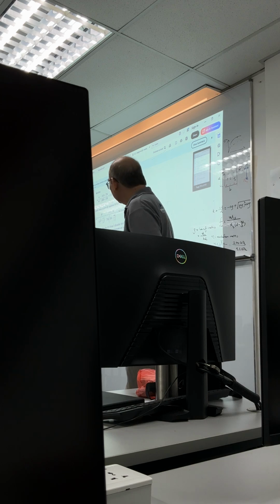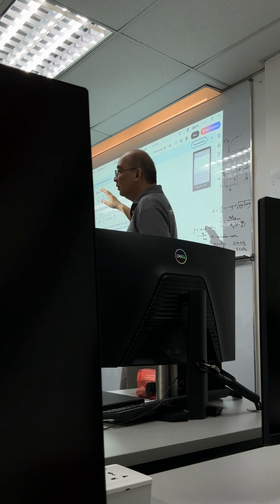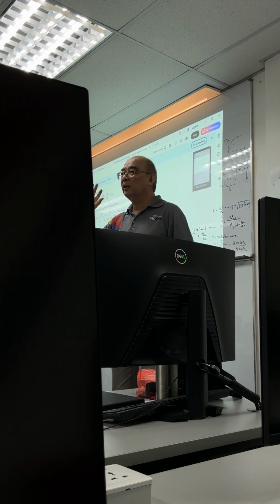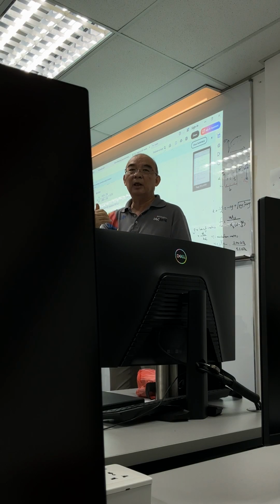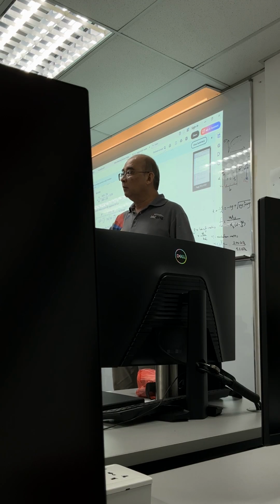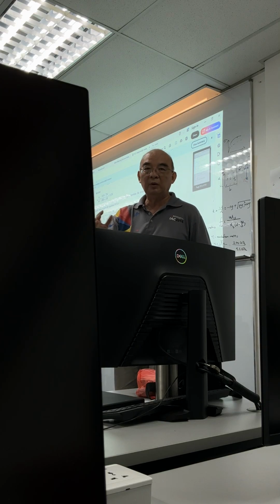Alright. Now, here he calculates rebar stress. From rebar stress, then he compared with the allowable rebar stress and says, okay, whether the crack width can be controlled or not. Okay, whether the amount of reinforcement that we provide can control the crack width below 0.2 millimeter or 0.1 millimeter. Okay? Right.